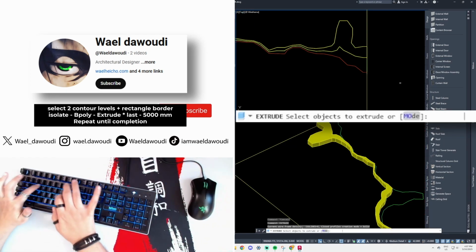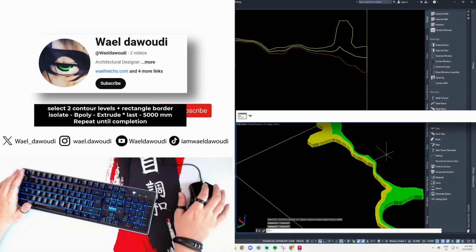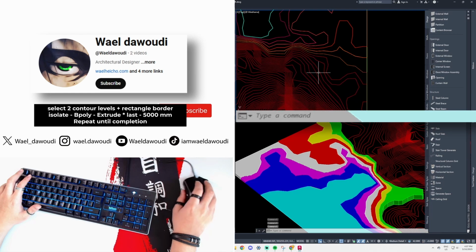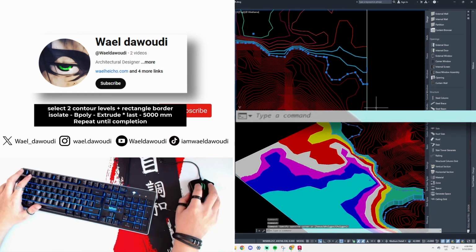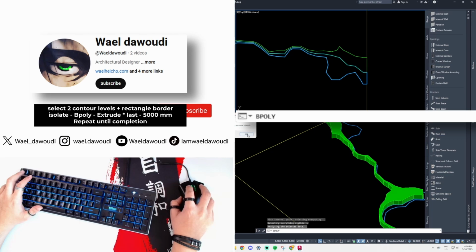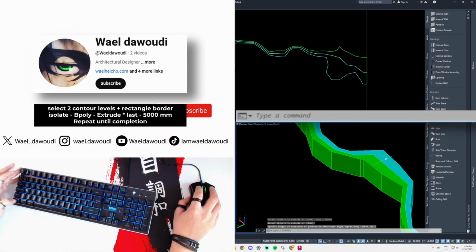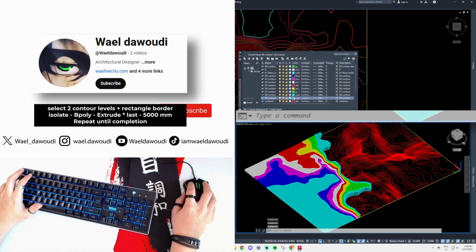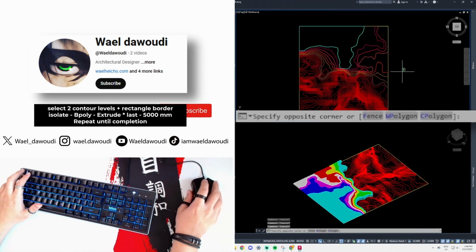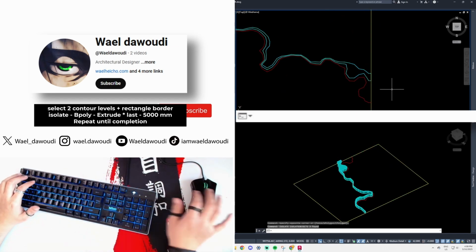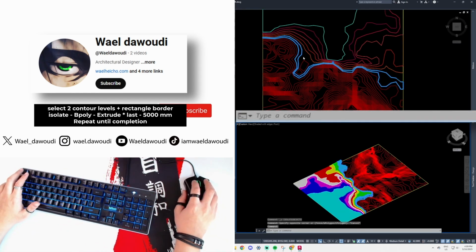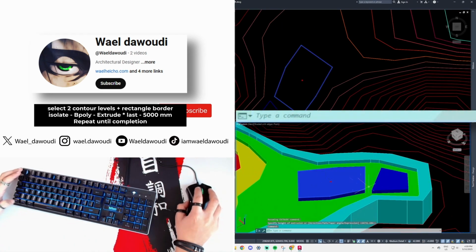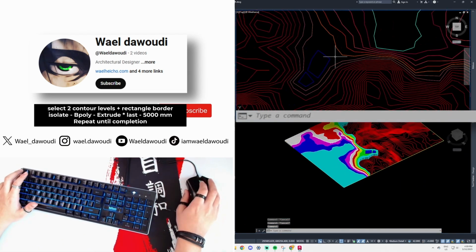So now fast forward, we have reached the last couple of contours that I'm going to make for this video because I do not want to go on and make all of them without making sure that the scale is correct. So for this, I'm gonna need a camera. I need a human scale to compare those contours to because I need to make sure that the height of the contours, which is 5 meters, is proportionate to the width of the scale of my project. So I do not want my contours to have a width of a scale that's less than the actual 5 meters in real life, which is the height of those contours.